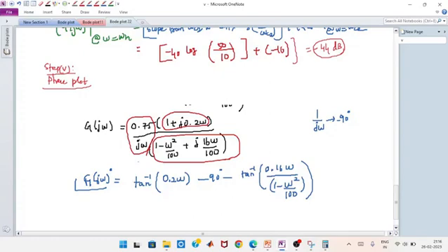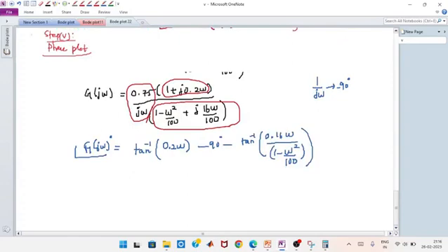Okay. So this was the thing. Now, again, tan inverse values vary from 0 degree to minus 180 degree, but our calculator calculates tan inverse only between 0 degree and 90 degree. Hence, I am going to make the correction: a 180 degree phase shift should be added after every value of omega n. What is the meaning, sir? That I will tell you while you are solving the problem.